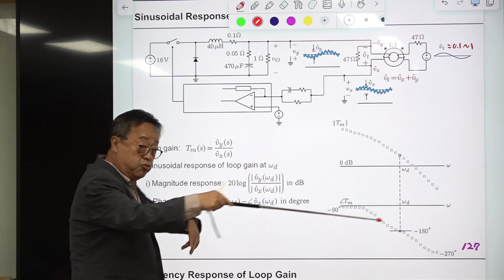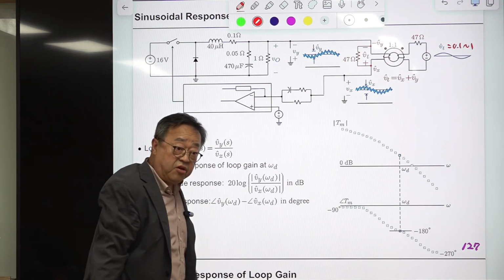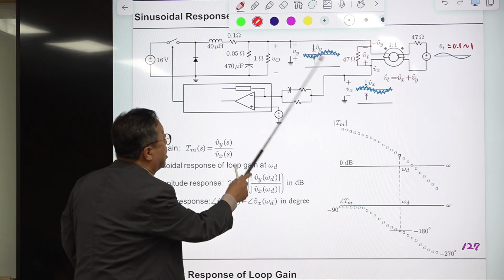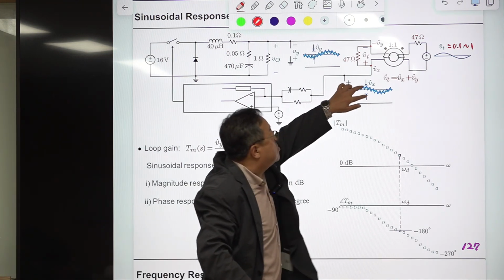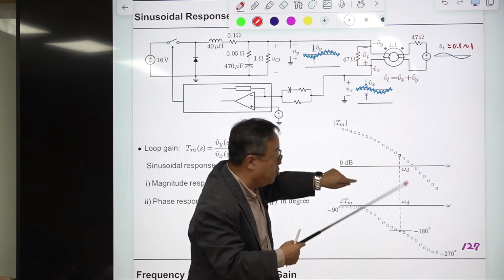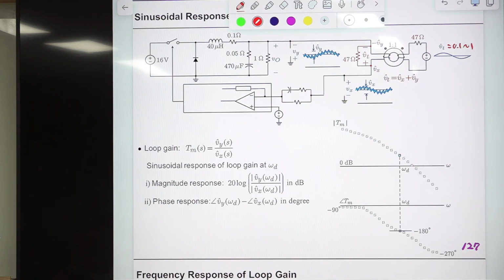If you don't have that equipment, the impedance analyzer, you use a signal generator, a sine wave generator, and you manually change the frequency and measure this with the scope, and you estimate the magnitude of this, then you plot this, and you measure the phase in between, then you plot this. That is the way of doing this in the past. In the 1970s or 80s, most people used this, and everything is now coming in as one piece of equipment, the impedance analyzer, with many other fancy digital features.